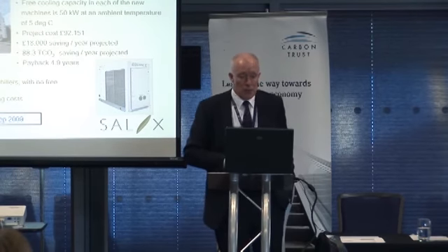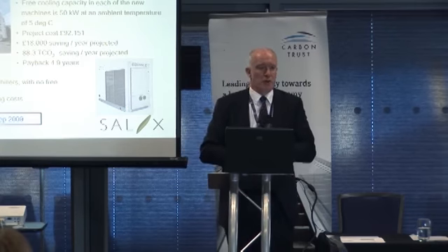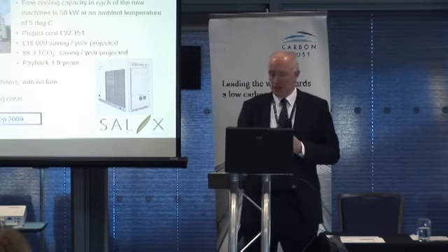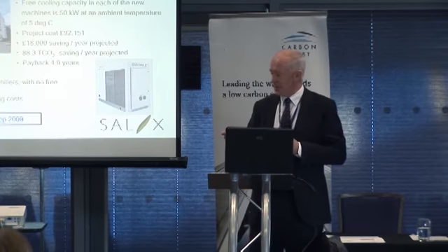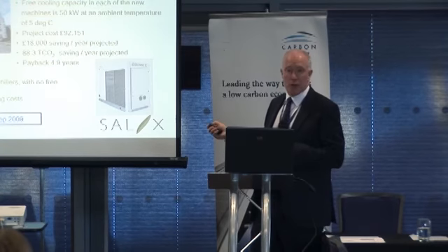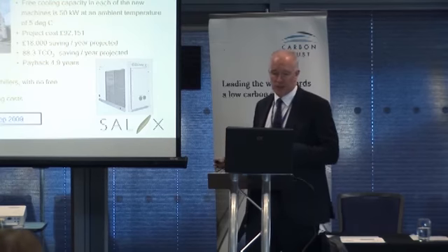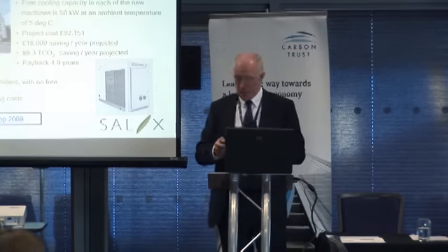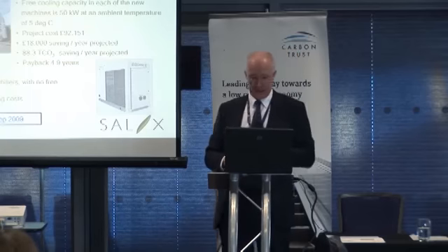University of Aberdeen replacing chillers, using packaged free cooling chillers. And obviously it's quite a cool environment in Aberdeen up there, a little bit cooler than here, but these machines can give 50 kilowatts of free cooling at about 5 degrees centigrade outside, which allows them to do a lot of free chilling on their servers, and again they're coming out with about 5-year paybacks.